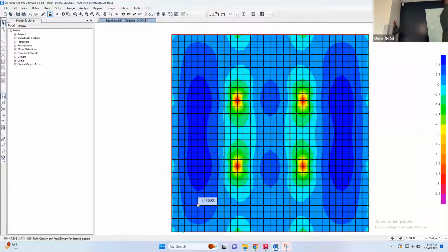You guys know what is the direction of this moment? Is this the moment that shows the beam is bending this way or this way? If I'm taking a strip, M11 is this way, it is X direction. So if I take a section here, it will show you the bending moment of the beam is something like this. And this is the actual bending moment. But if you take a strip here, it will show you a random moment. Okay, so this is what we are looking at.